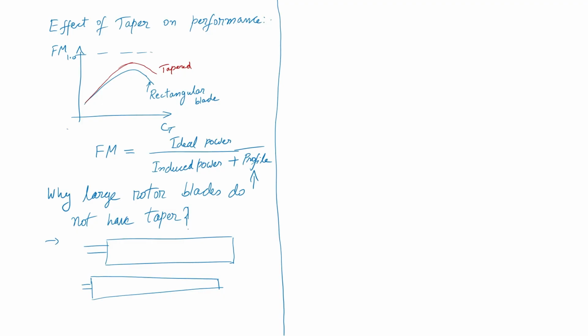Okay. So now I will introduce one more very important concept. Then we will look at the tip loss factor, because right now my BEMT has given me an inflow which does not account for tip loss. It says my lift is maximum at the tip, which is not the case; lift has to come back to 0 at the tip because of the tip vortex. Then we will study the performance part, helicopter performance, like we did fixed wing performance, where we talked about endurance and range. So how do we analyze endurance and range for rotary wing systems, be it a quadcopter, helicopter, single rotor, twin rotor, whatever. These are the main topics remaining.